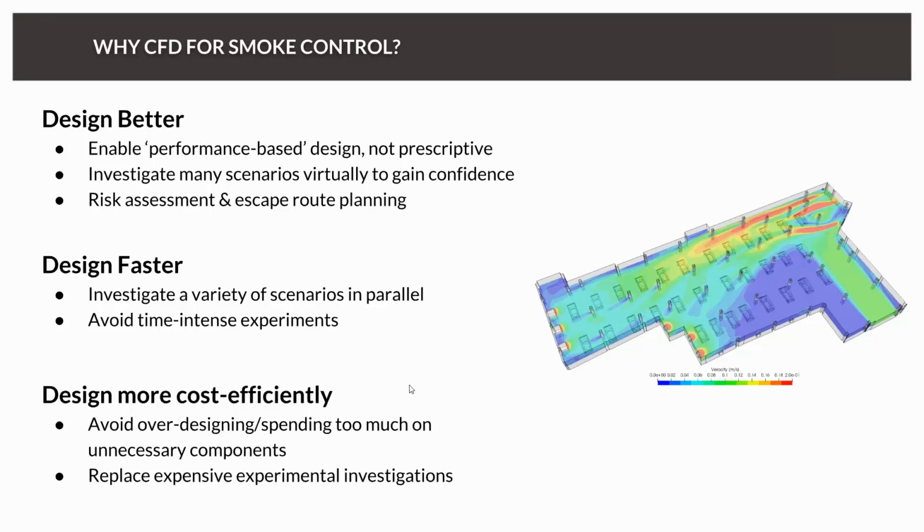And for sure, you can choose if you want to simulate a transient or a steady state case. This is basically just a user's decision. And in a lot of cases, by the way, a steady state result actually gives you the same kind of information as a transient simulation. And just in, let's say, very special cases, it's really necessary to simulate it in transient, which for sure takes much more time and computational resources.